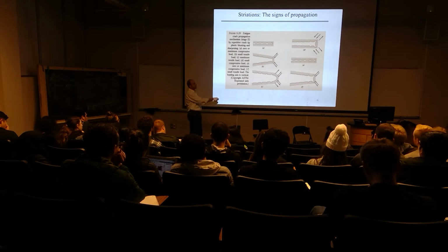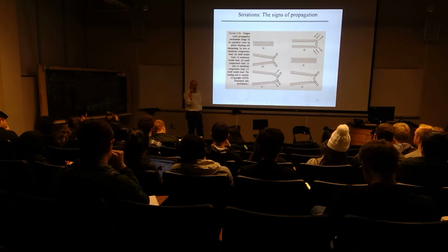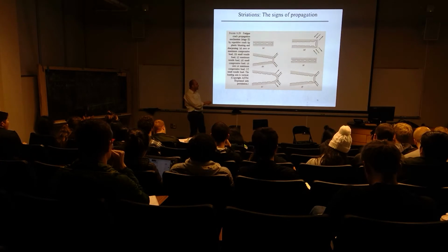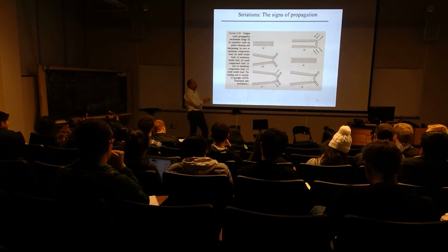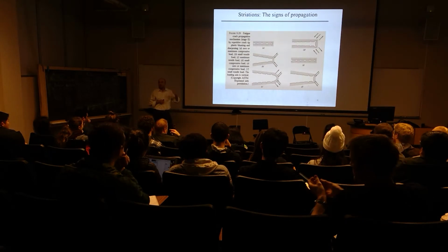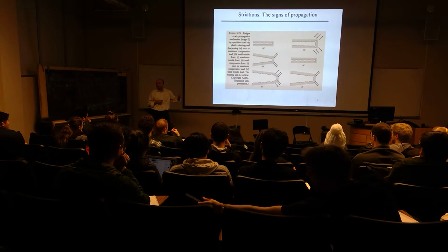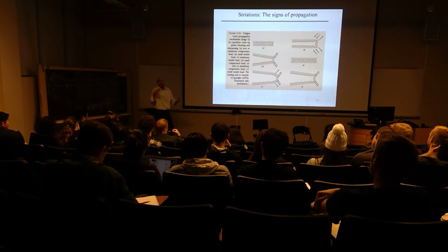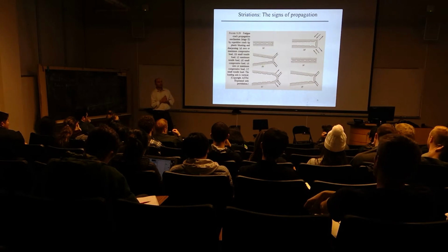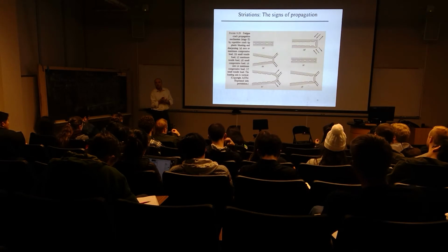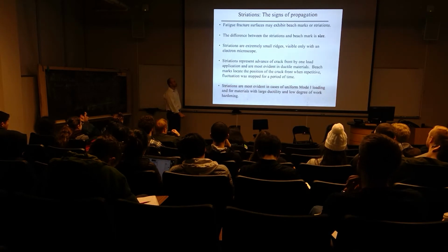So when the crack actually becomes zero stress, you get that little nub in there that's just really a result of that small amount of the elongation that occurred around the surface of the crack. And the process then continues to the end. So each time you get a cycle that's large enough to introduce plastic deformation near the crack tip, you get that signature of the crack saying, I moved a little bit, but I was subjected to enough deformation that I actually extended my surface area. So that says if that's the mechanism, then ductility is a big requirement for seeing striations. And indeed, that's the case that we see.